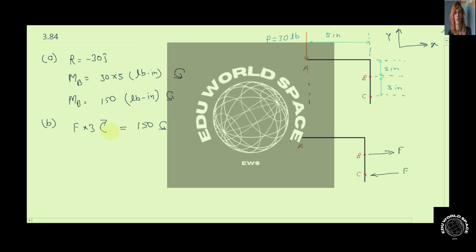So if we remove the signs of counterclockwise and clockwise, we can write it as minus F into 3 is equal to 150. So the force comes out to be minus 50. Sorry, in this problem the unit of the force is pound, so minus 50 pound.